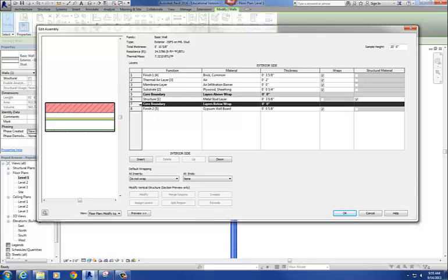The reason why you want to do that is for dimensioning. Typically when you dimension a wall, you always dimension to the first material that's put in for that wall. So for example, if you have a metal stud construction in your building, the first thing that they're going to put in as a part of that wall is the metal stud. Right, they're not going to put the chipboard in first. They're not going to put in the brick on the outside first. They're putting in the metal stud, and it's usually the structural portion of that wall. So when you're dimensioning those walls, you want to dimension to that first material. It doesn't make any sense when you're dimensioning a series of walls to dimension to the chipboard, because then when the guy's actually putting in the wall, he has to subtract 5/8 of an inch or a half an inch from that dimension.